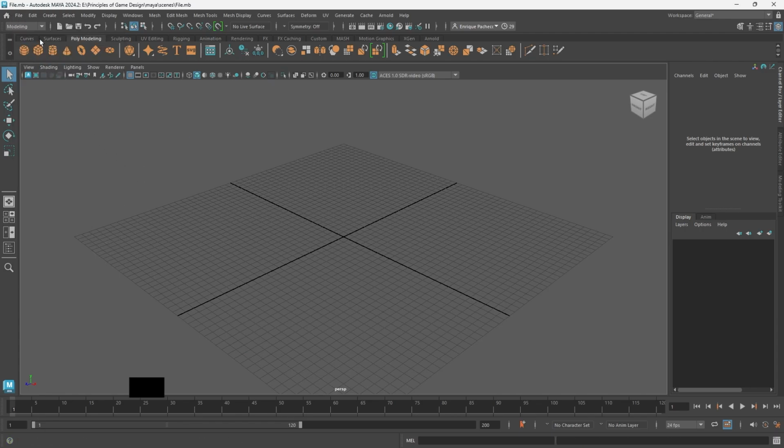And now let's try and test that Increment and Save, that Control-Alt-S. I'm going to change something about my scene, and if we pay close attention to the file name up in the top left corner, I'm going to click this cube button, for instance. And now our file name in the top left corner has an asterisk, which means we haven't saved recently. So I'm going to hit Control-Alt-S, and now my file has a little number attached to it. Let's go ahead and change something else about our scene. I'm going to hit this cylinder button, get that asterisk back, Control-Alt-S, and that number has gone up.